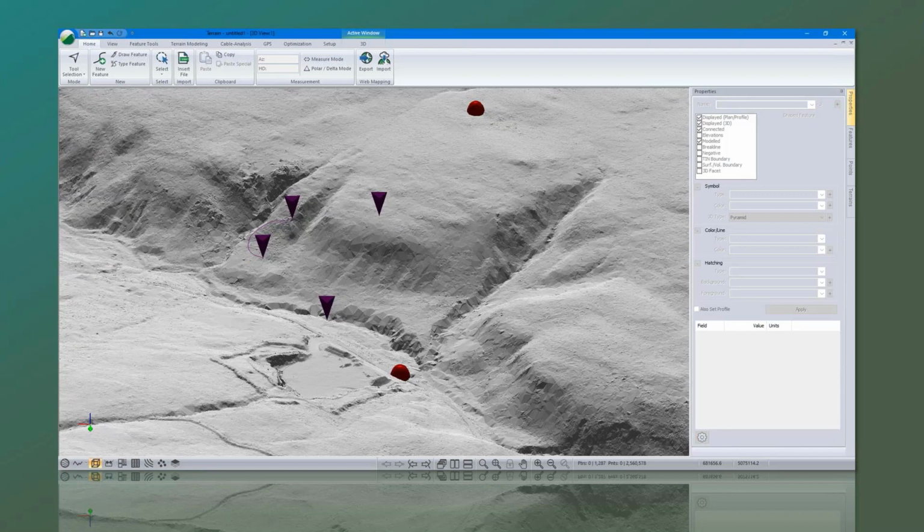And if it's a grade controlled road, you're often going to be running grade lines to see where you can get to from those other control points. So you'll spend that time locating those control points. And then once you've got the control points flushed out, you'll usually go through and play connect the dots in the woods, and fill in between those with the ribbon center line.